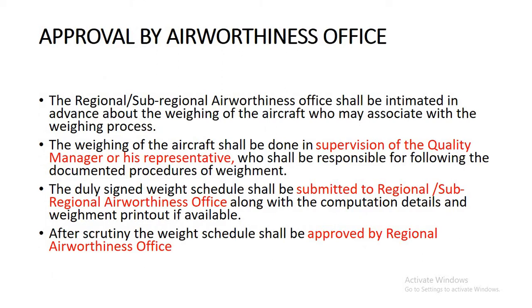Before you conduct weighing, you will intimate the regional or sub-regional office that you are going to weigh an aircraft. This weighing data is very important. If it goes wrong, there are a lot of implications. That's why you will inform prior to conducting it. Now, the weighing should be conducted under the supervision of a quality manager or his representative, and he will be responsible for following the documented procedure of weighment.